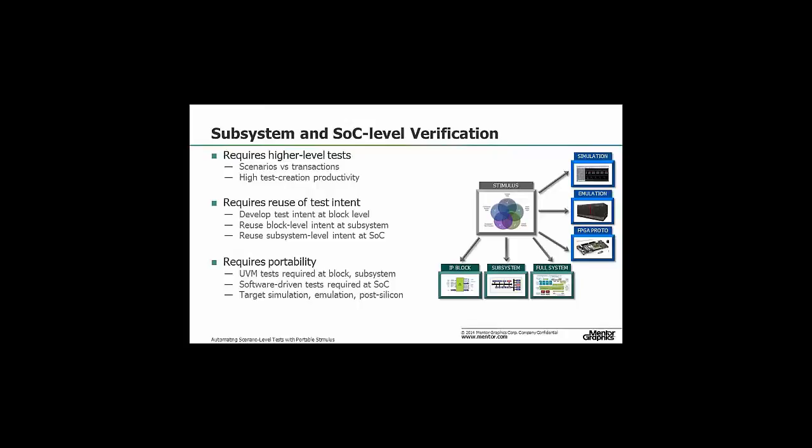So that's one dimension of reuse, going from block to subsystem to SOC. But there's also another aspect or another dimension. All companies doing advanced SOC design today use a whole range of different verification environments. Usually they start with simulation, moving on to emulation, later on FPGA prototyping. And every time this is done, they have to more or less start from scratch. How do you take your UVM test and run it on an FPGA prototype, for example? So these are some of the difficulties that this portable stimulus methodology is trying to address.